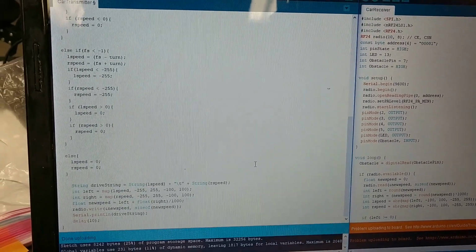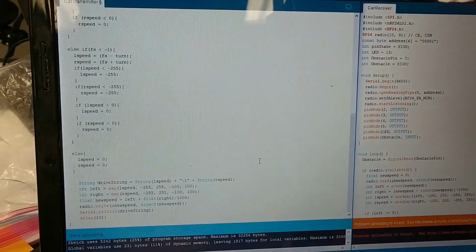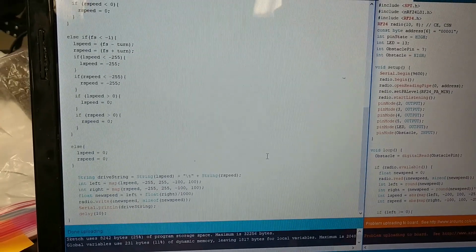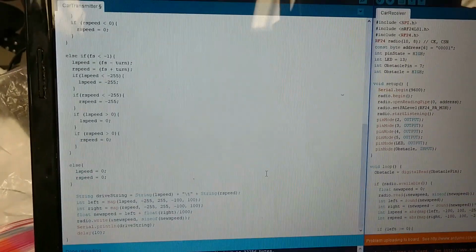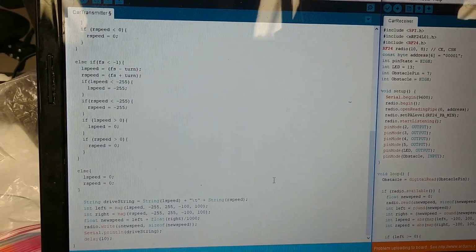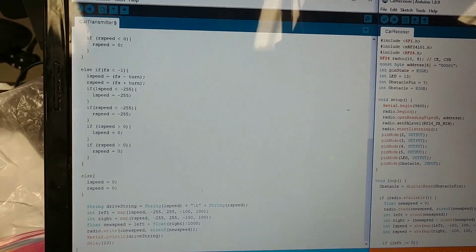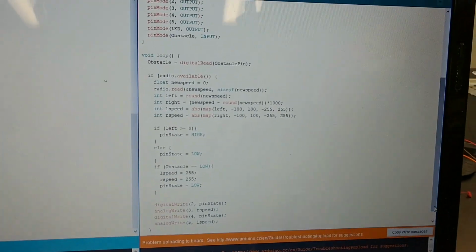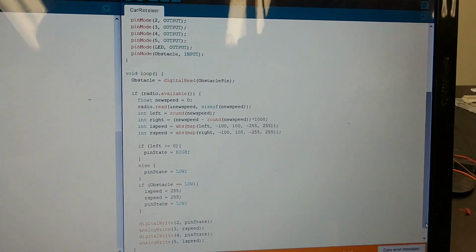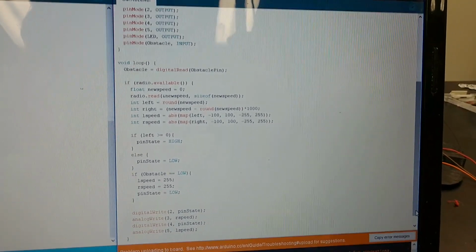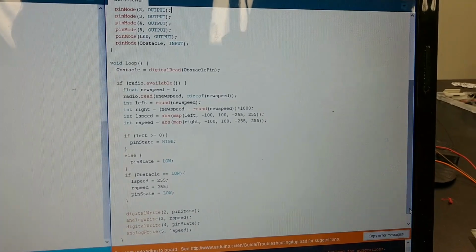At the end, I have a string to send to processing, and I have to create one variable with a combination of the 2 motor variables to send through my radio.write so that I can read one value at the end, which I then, using the same libraries, read and convert back to a PWM signal, which I use to determine whether to go forward or backward, and then if there's an obstacle, I send a separate signal to reverse away from it.